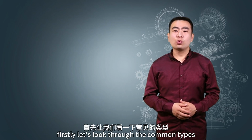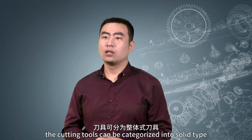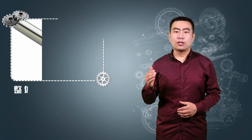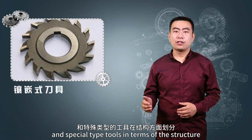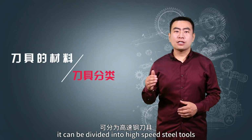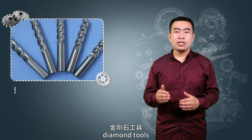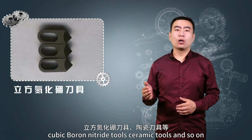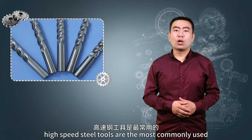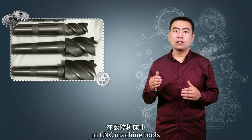Firstly, let's look through the common types. There are so many cutters. First, the cutting tools can be categorized into solid type, insert type, and special type tools in terms of the structure. Second, according to the material, it can be divided into high-speed steel tools, carbide tools, diamond tools, cubic boron nitride tools, ceramic tools, and so on. At present, high-speed steel tools are the most commonly used in CNC machine tools.